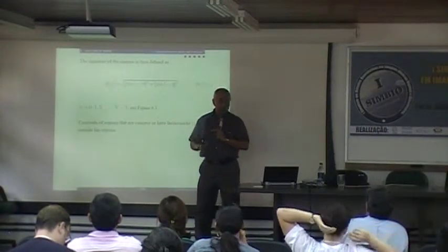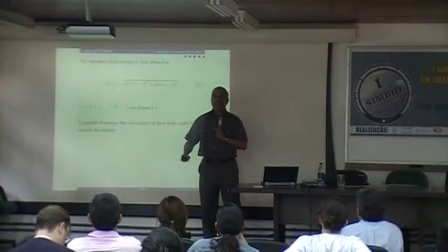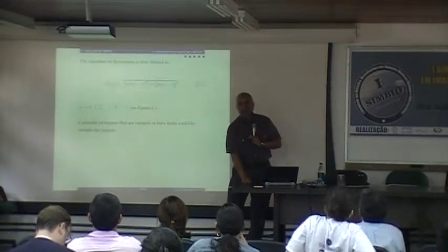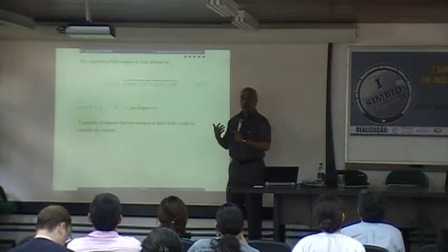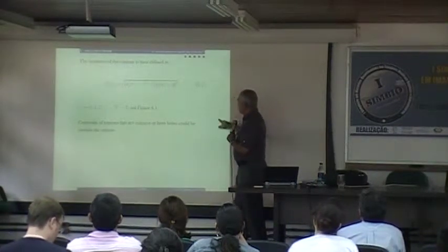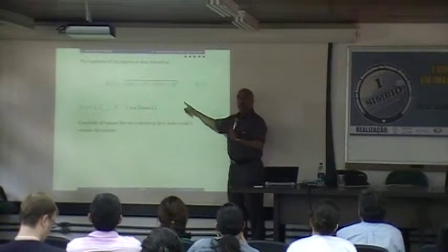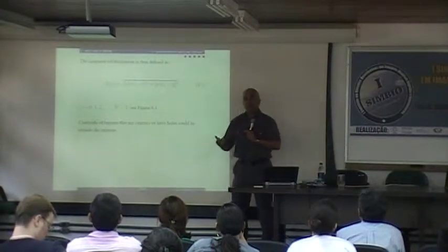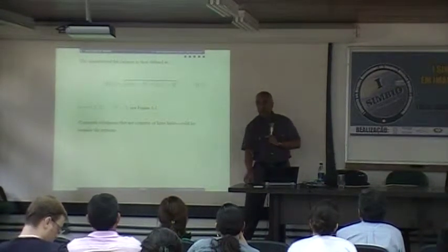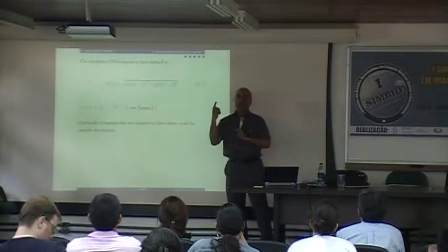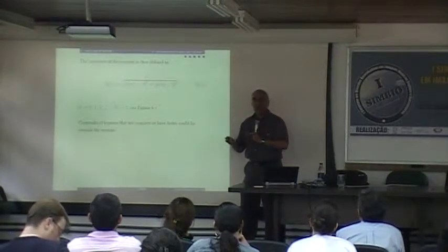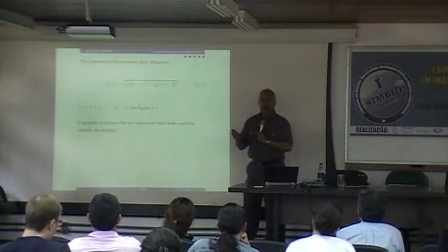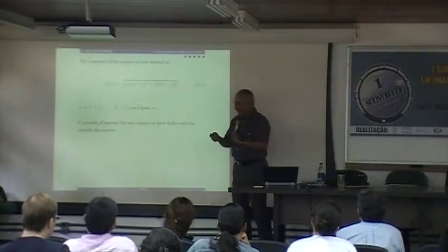But sometimes the centroid may be outside the object and it may not have any meaning because it is not a physical point within the object. For example, if you have a crescent moon-shaped object, the centroid is outside, which means there is no point on the object that can support it in a stable way. So then, do you want to use that as a reference? I don't know. So there is a question mark.